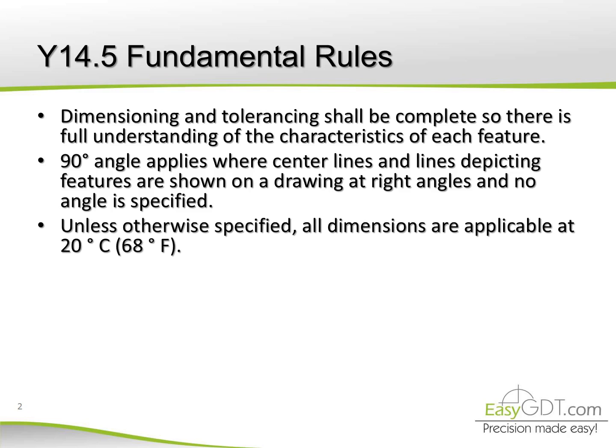Unless otherwise specified, all dimensions are applicable at 20 degrees Celsius or 68 degrees Fahrenheit. Remember that materials expand when heated. That's why it is important to define a standard temperature. That's why metrology labs have a well-controlled temperature.